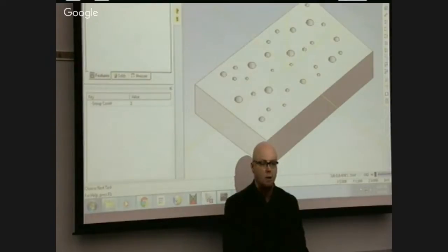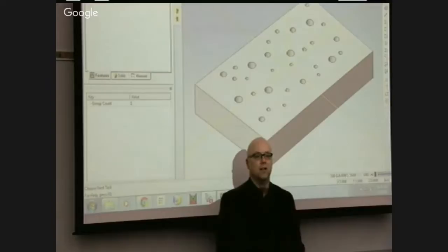We want to automate our code creation. We created our cutting operations based on the tools that we selected and the P-top features. I like simulate. Although in a fully automated system, we might skip the simulate step. I'm not sure. No, I think I would simulate it. Because if you simulate it with collision detection turned on, it will throw an error if it crashed, right? I think we should simulate it. Just say it doesn't crash. All right, simulated. Okay. What's next?